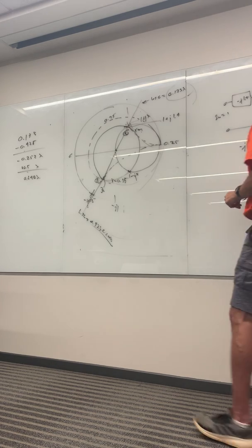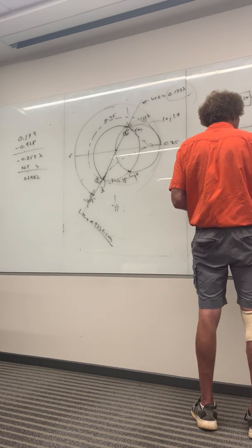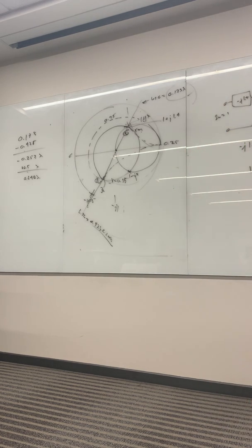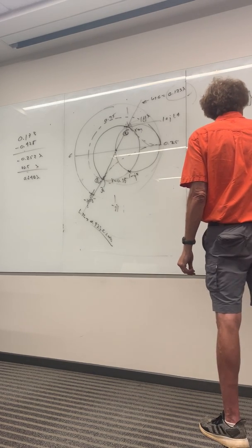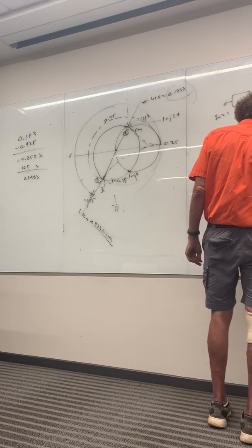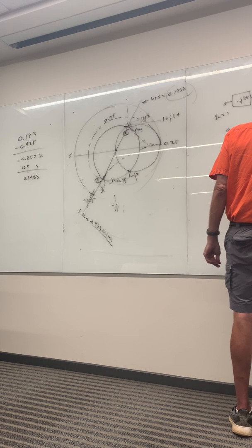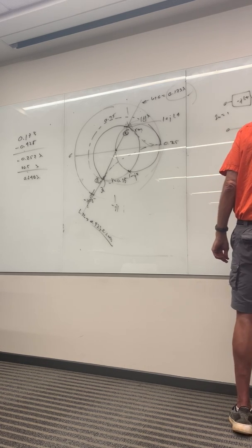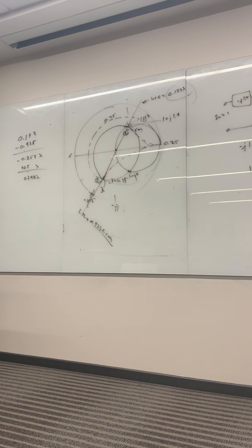Which means now I have 1.4 equal to 1 over omega C Z naught. We can get omega because he gave us the frequency of operation as a gigahertz, can't we? Right? And he gave us Z naught as, what is Z naught? Is this 50? Or is it 100, right? So now I can say that my value of the capacitor would be 1 over 1.4 times omega, which is 2 pi times 10 to the 9th, because it's 1 gigahertz, times Z naught, which is 100. And now you can tell me the value of the capacitor, which is very, very small.